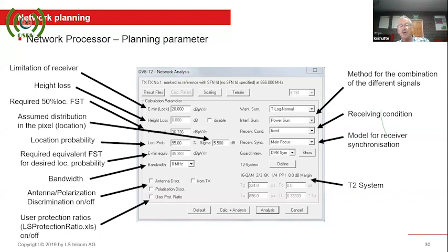So it will tell you you are currently using a 16 QAM modulation, 2/3 forward error correction, 8K carrier scheme, 1/4 guard interval, and pilot pattern 1. And there's no implementation margin. Sometimes you want to introduce an implementation margin to cater for additional losses within the system or to calibrate your propagation model.